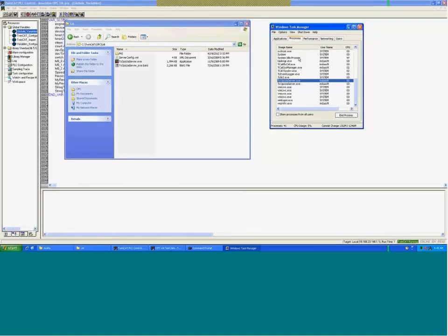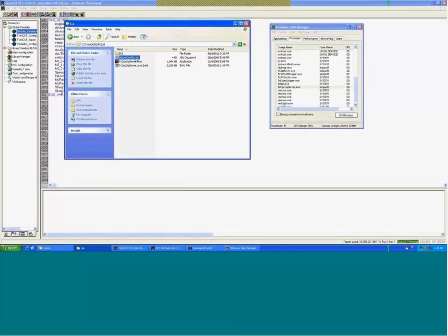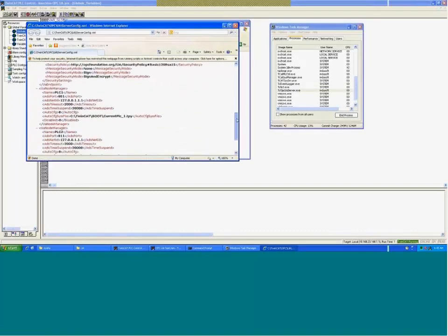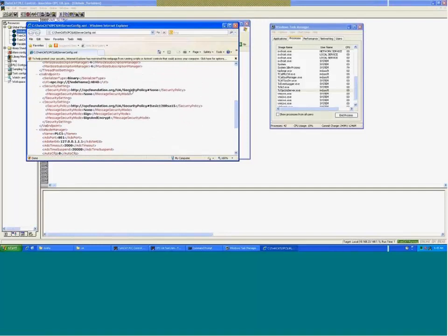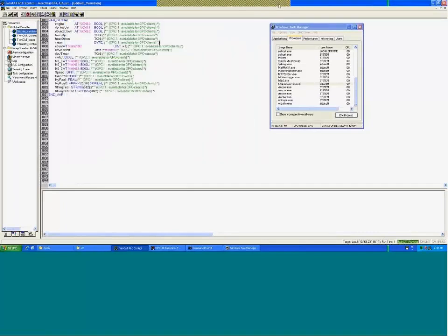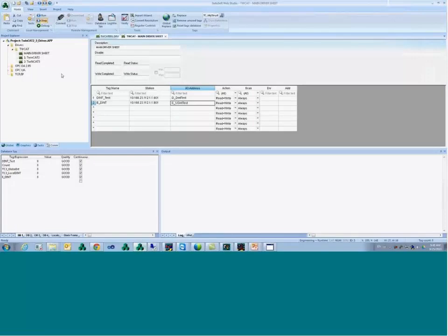All right? So on the InduSoft side, what you would do, actually I have 2 running, is enter the URL that is configured here and the port number. So it would be opc.tcp:// and then the node name, so it would be the computer name, colon 4840. So if I go to the Web Studio application here, I go to OPC UA, I create a connection.